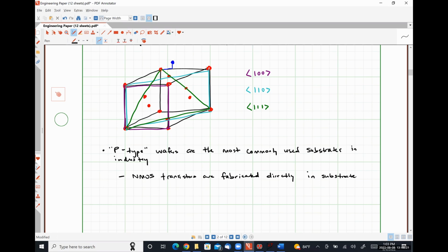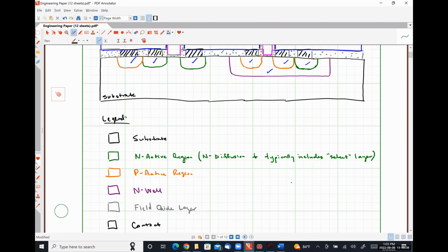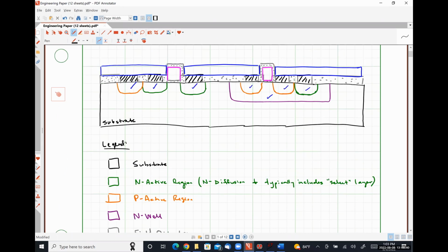What about P-type transistors? Since we're dealing with CMOS process in this class, I'm going to just say PMOS from here on out. So how do we do a PMOS transistor if we have a P-type substrate? Well, let's scroll up and look, because we've already seen it. We put it inside an N well, where the N well serves as a local substrate for that PMOS transistor.